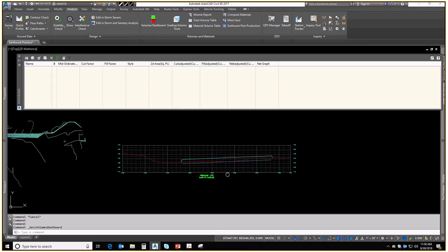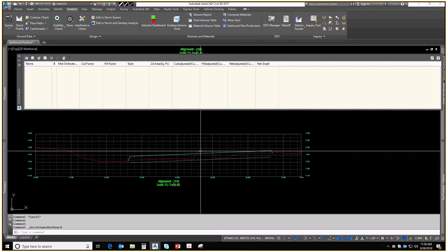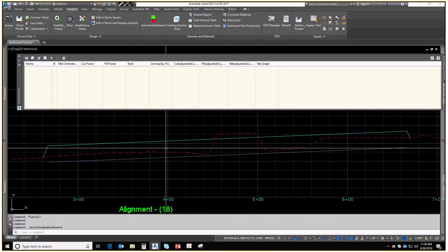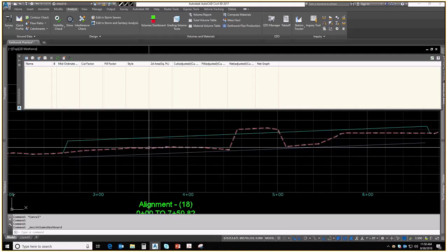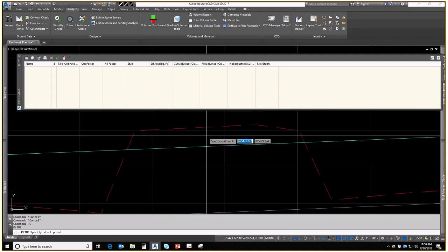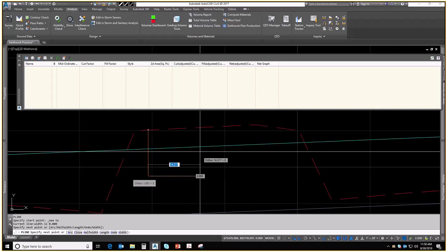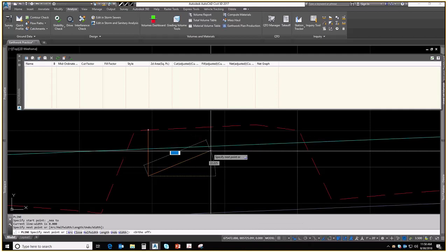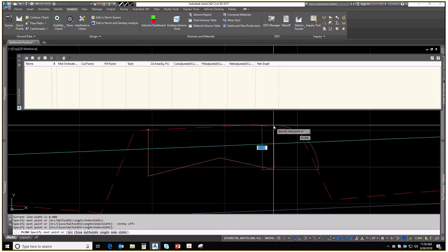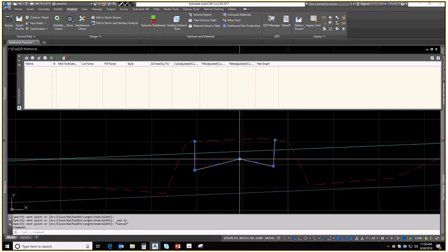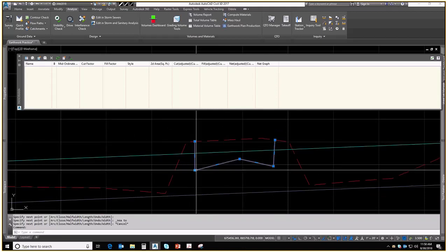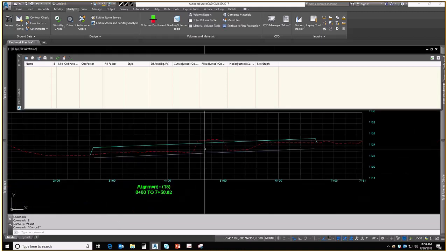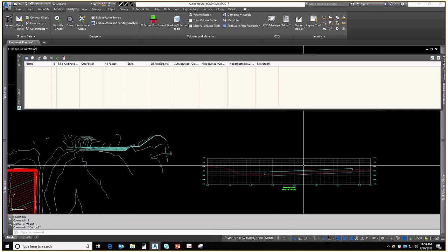So for now, we're going to assume that there is no pavement that we're removing. If you were adding pavement to be removed, you would do the same thing. You'd model out your, say this here was a taxiway. You'd model out the subgrade accordingly. So just pretend it looks like that. So you would model this out, and then this line would then come down and trim out this inner portion. But for now, I'm going to pretend like there's no pavement whatsoever.